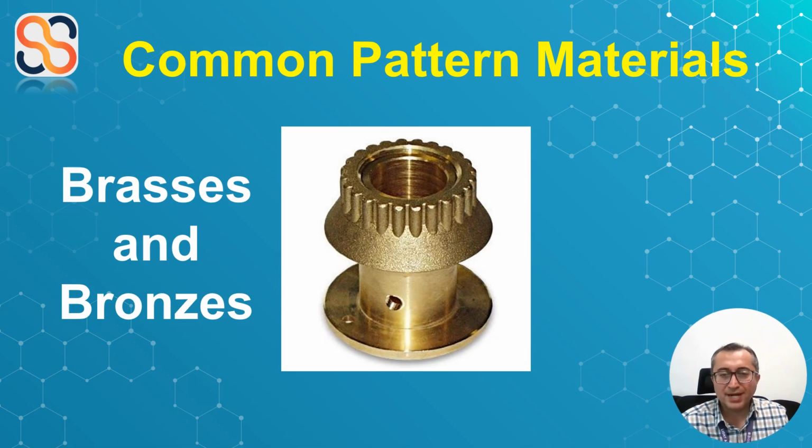How about brass or bronze? Actually, these metals are heavier and more expensive than cast iron, making them suitable for smaller castings. They have good strength, machinability, and resistance to corrosion and wear. They also provide a better surface finish, particularly in match plate patterns.